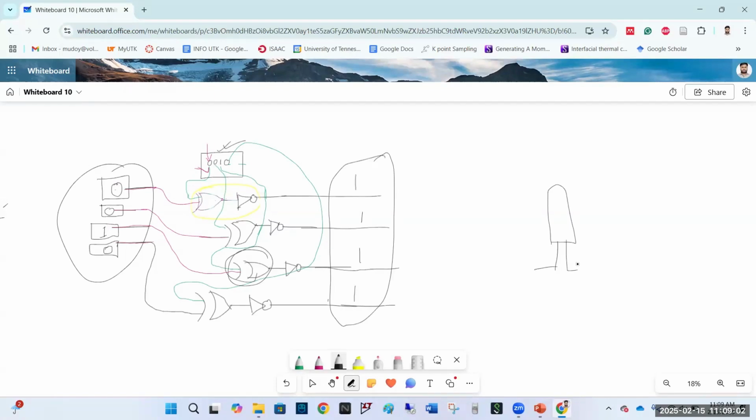Typically an LED will have two terminals. The one terminal will be grounded. This is the common ground of the circuit. You will have a ground in your circuit, and you need to connect this ground. And the other terminal should be your input actually. So if the LED gets 1, high voltage, then it turns on. But if it gets 0, it will not turn on, it will be off actually. So to turn this light on, we need to insert 1 here.